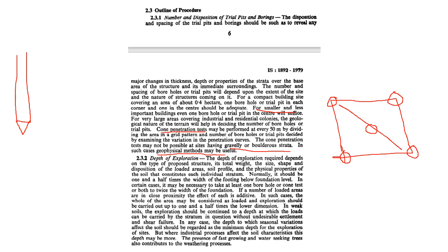So what you can do is place this cone instrument at the ground level, and then by means of drilling equipment, you push it in. These are extensible rods, you can add on rods to it. There will be provision for adding more and more rods to this instrument so as to reach a particular depth.